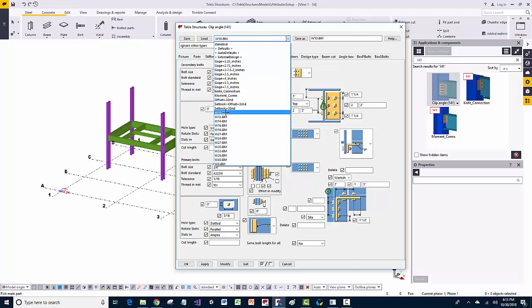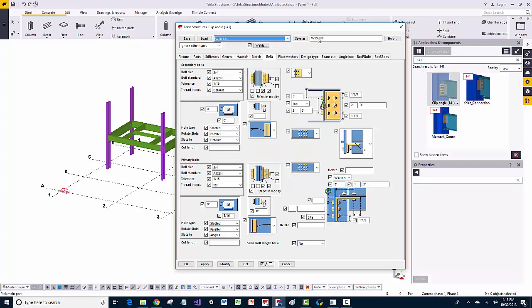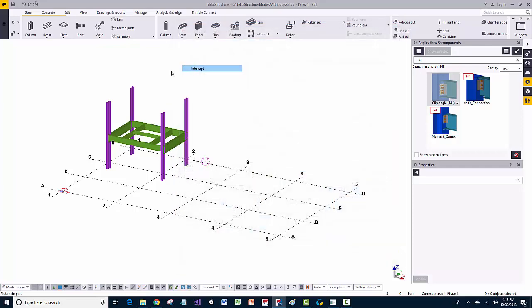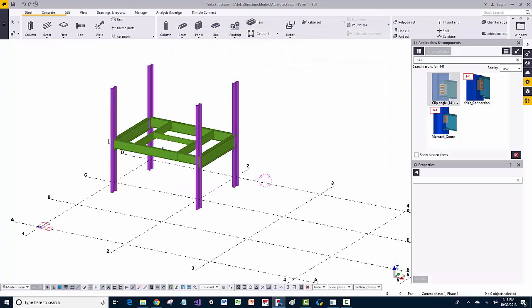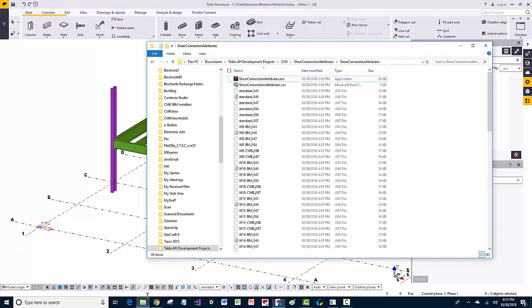So what we want to do is use the same naming convention from job to job. There's always going to be a W10 in the connection schedule, W12, 14, 16, etc. And you might have variations of this for specialized connections based on a connection mark in the connection design. But either way, you're going to have usually a pretty consistent naming convention here. So let's go ahead and go into controlling how we can actually set those up and change those.